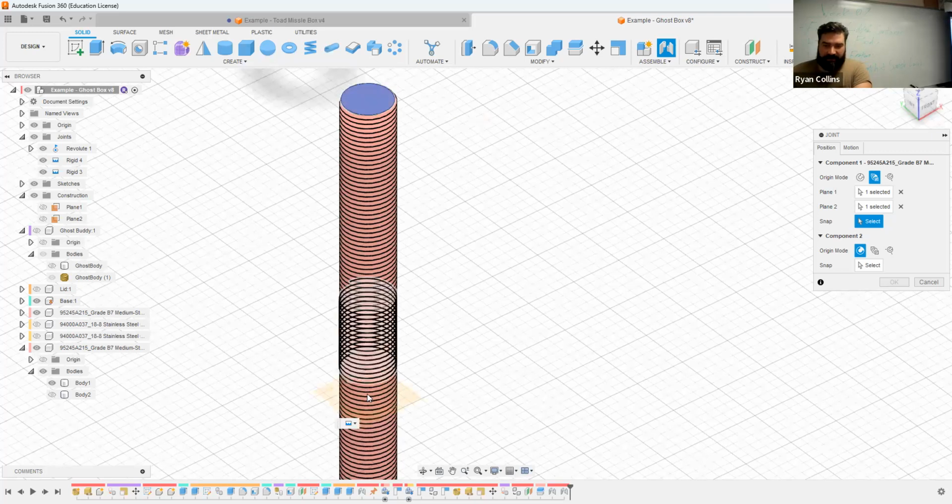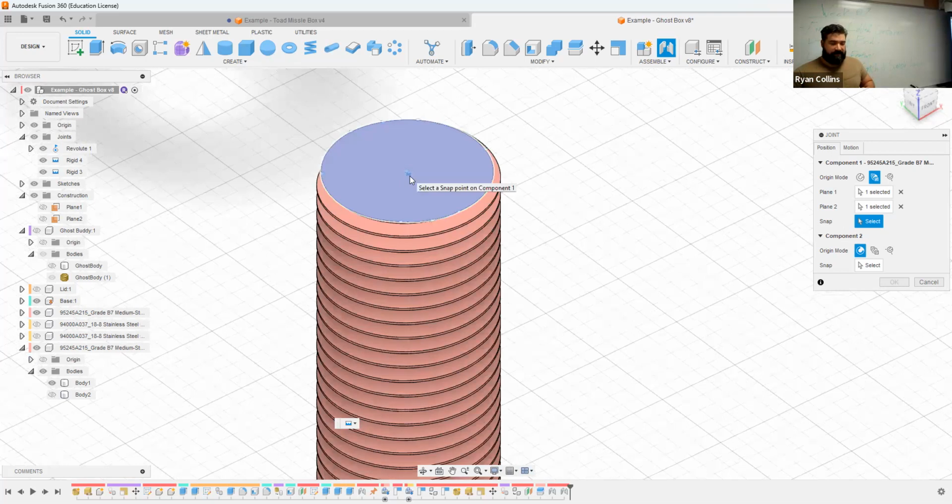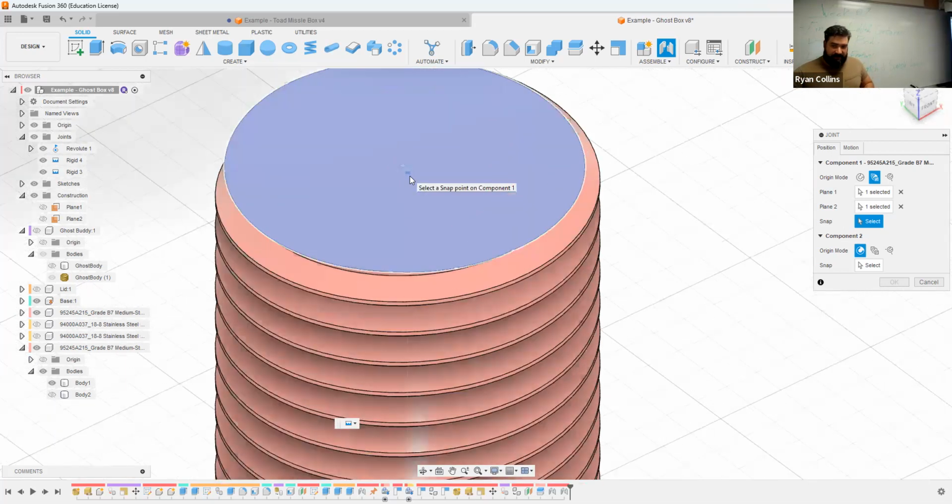If you can't get to it because these threaded rods just throw your selection all over the place, the program knows that you're selecting something right between the middle of those faces, so you don't really have to select actually in the center of the spot. You just have to select now in the center of the cylinder. And you can see as I zoom in, you can vaguely see that little dotted construction line running right down the center of the threaded rod.